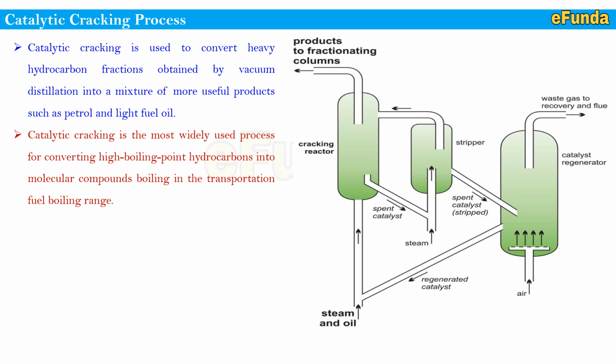In this process the feedstock undergoes a chemical breakdown under controlled heat of 450 to 500 degrees Celsius and pressure, in the presence of a catalyst, a substance which helps to promote the reaction without itself being chemically changed. Small pellets of silica, alumina or silica magnesia have proved to be the most effective catalysts used in this process.